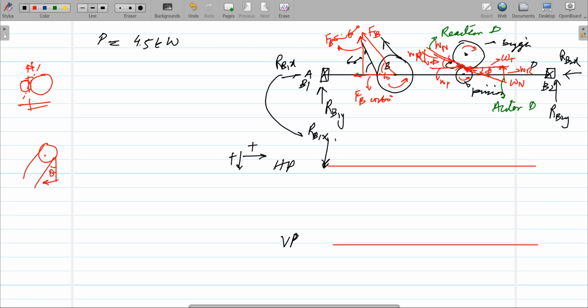So this is your first force, that is this. The second force is actually like this, in the opposite direction. Because of this opposite direction, we can draw the force in the opposite direction as well. So this is FB, and this is cos 60 degrees. The third case, if you look at the horizontal force, this is a tangential component.